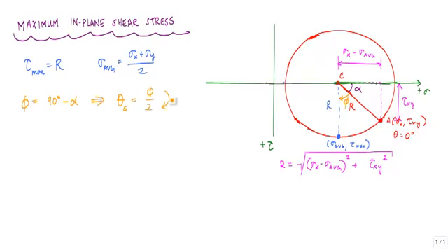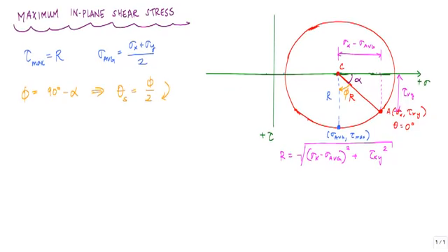And my stress element will look like this. From theta equals 0, I will rotate theta s. This was theta equals 0 degrees. And again, using this new line, I'm going to draw my stress element. The first line I'm going to draw is a line normal, or perpendicular, to that new theta s axis. And from there, I will draw a square. Hopefully that looks square-ish.